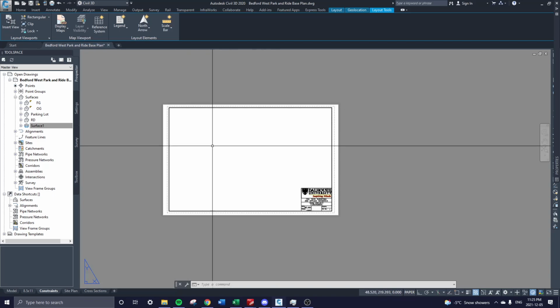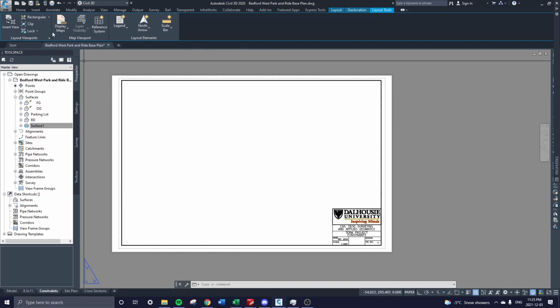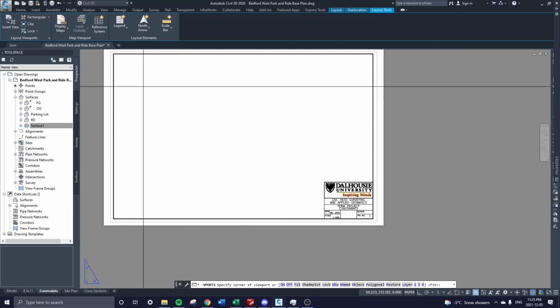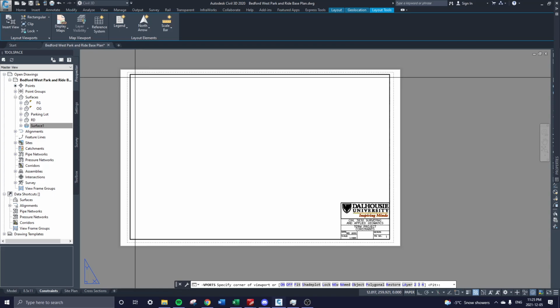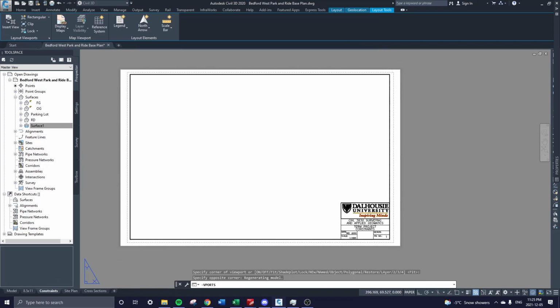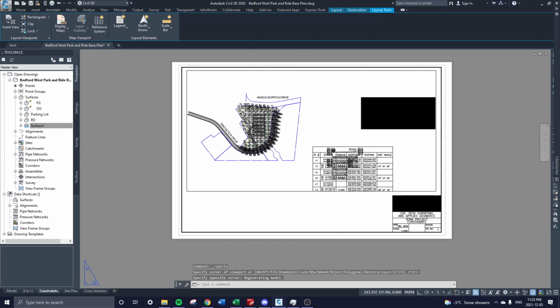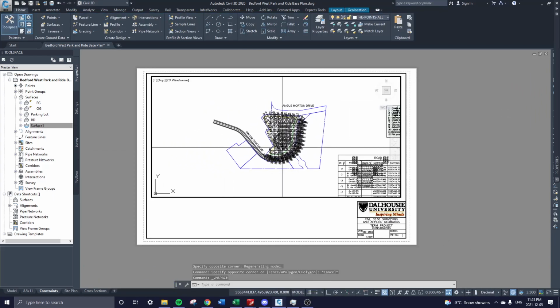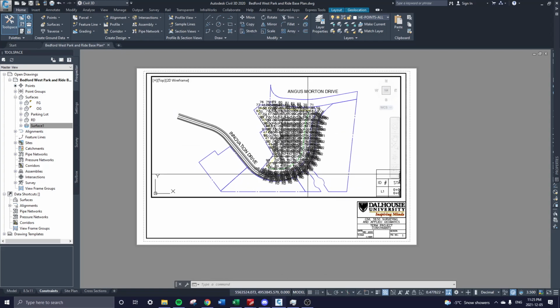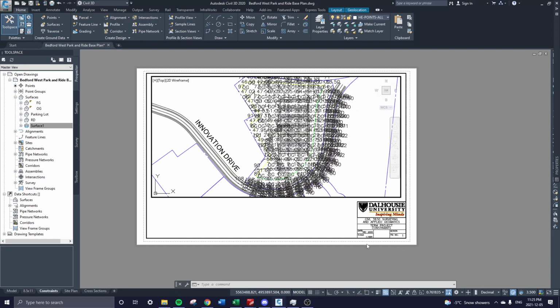And what we're going to do is create a nice good old viewport, which is going to be rectangular. So hit that button. It's going to ask you for the corners. This is basically like drawing a window into what we've drawn in model space. So nice little window here. Okay, cool. That just populated, and it looks pretty crowded, doesn't it? So just zoom in until you have a nice little area. I think he wants the scale 1 to 1,000.